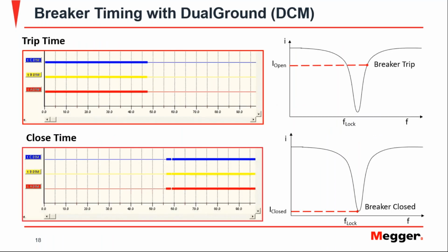The other big advantage is that you obtain the results in the traditional way that you get the results from conventional timing, because you are monitoring the same thing. You're monitoring a current, and you can even see those little bounces that may happen if there's any kind of lack of pressure in the contact, in the fixed contact. So it is a very practical way to see the result.